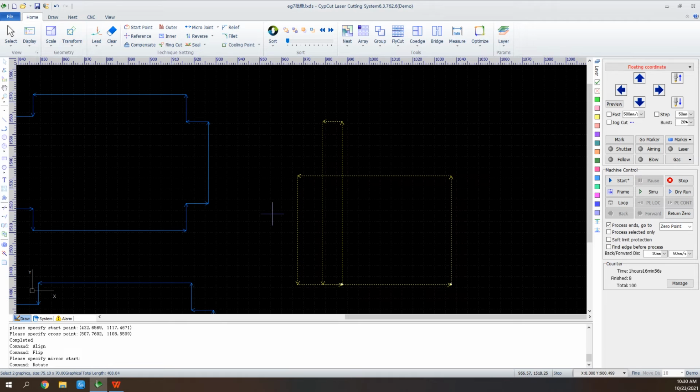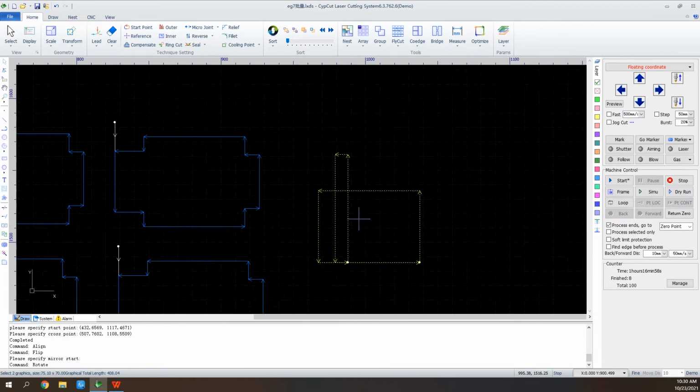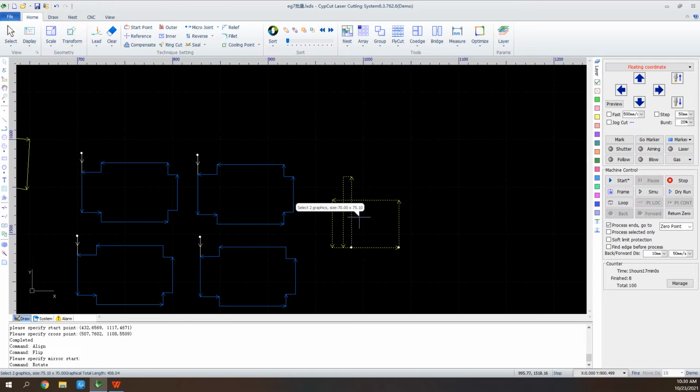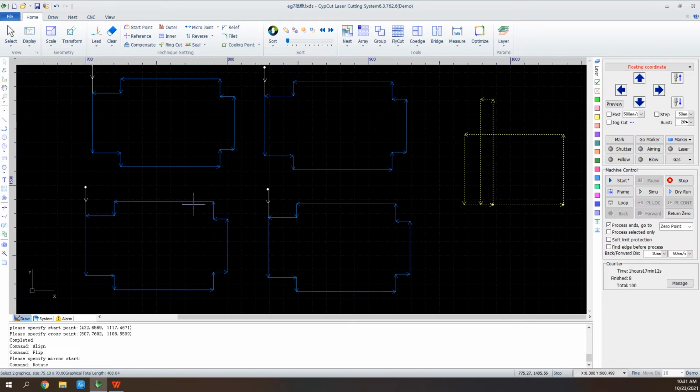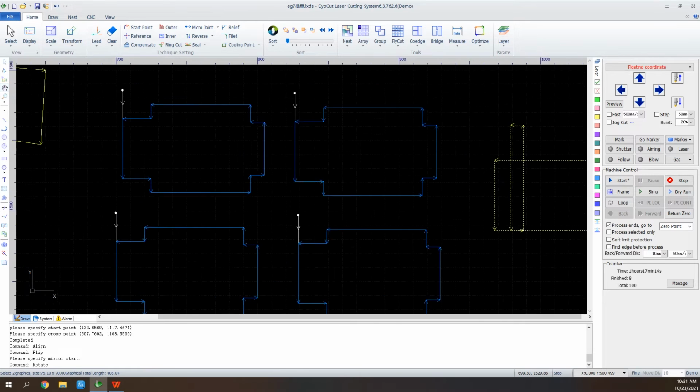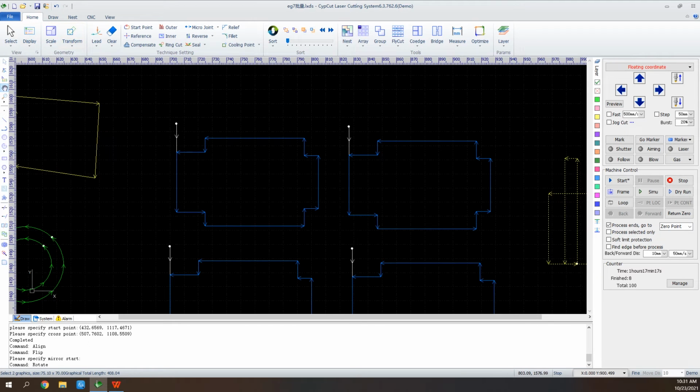And when we laser cut parts, we make the cutting path start from several millimeters away from the part. This way it can get cut much better. The distance is what we call the lead. When we set a lead, first we select the graphic, then click the lead